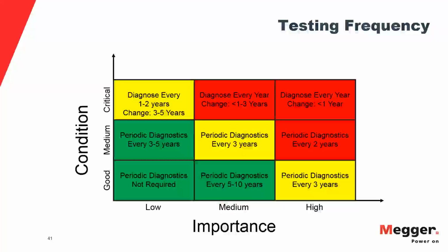By noise, do you mean in the audio domain or high frequency noises? No, very much not audio noise. By noise, I mean signals in the range that partial discharge would be present, which is some hundreds of megahertz. Corona is very similar to partial discharge. So if you're in a switch yard and there's some corona going on, that can induce signals into your test equipment. Something like a switching power supply in a computer might have enough high frequency components in there to affect you. Some hundreds of megahertz type of signals are inducing these signals into your test equipment.